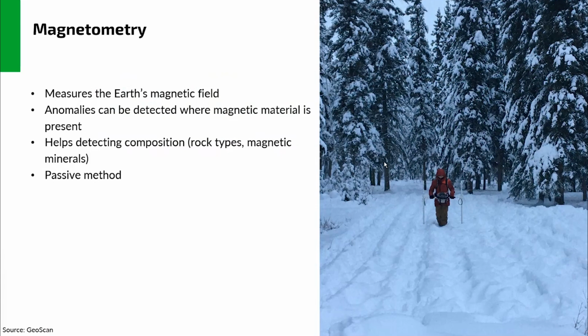Therefore, we have to be careful even when we are wearing the instrument to make sure that we are completely demagnetized, which can sometimes be a challenge, but we have to make sure that we are completely free. Otherwise, due to the sensitivity of the instrument, it's going to be a completely useless survey. It is mostly used in archaeological surveys and some shallow geological surveys. Volcanic rock delineation, for example, is one of the examples where we can use this particular method. But again, it's very sensitive.